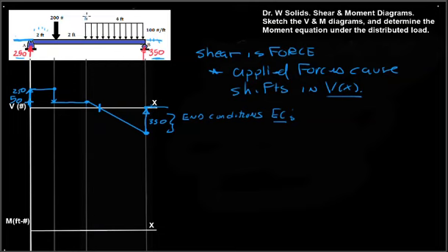So let's define a new variable u, which I'll use just to measure from here. So we can say then that u times 100 pounds per foot has to equal 50, which is the amount that we have to offset this by. And we find that u will be 1/2 a foot.